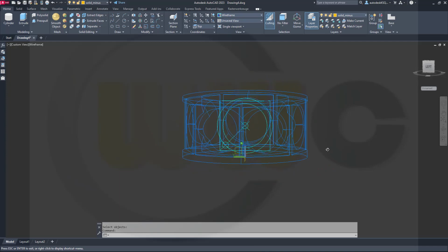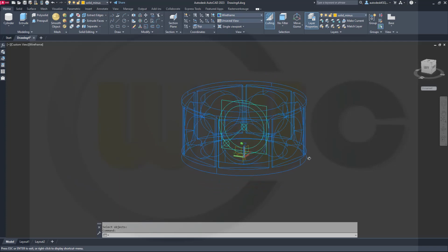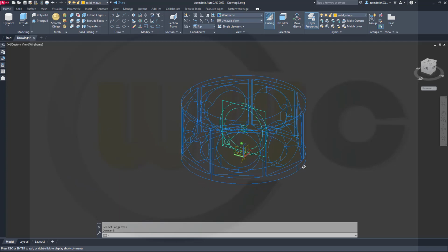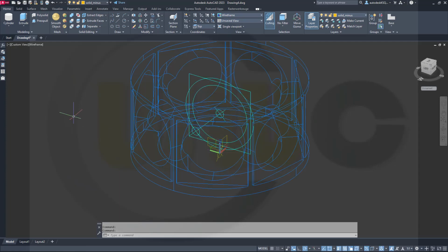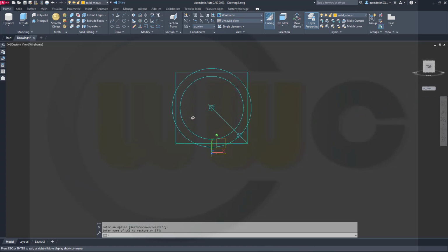Now let's take a look. I will need a cylinder, and this should be patterned and then patterned again. Okay, I could hide this solid, at least for the moment. Okay, let's switch to the YZ view. And I should look from this side. Yes.